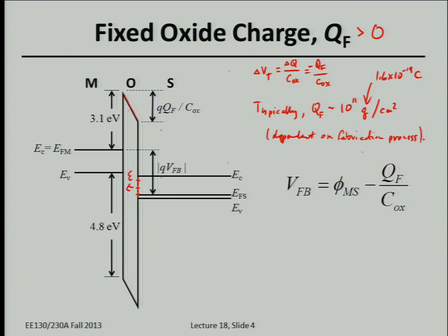So this energy band diagram shows you the flat band. If I give you this energy band diagram, you should be able to tell me it's a flat band MOS band diagram. That's because the definition of flat band is that the energy band diagram is flat in the silicon. Now, the reason why it's not also flat in the oxide is because of fixed charge or some charge at the interface. So qualitatively, if somebody were to show you this band diagram, you should be able to tell me there's charge at the interface between the silicon and silicon dioxide, because there's an electric field existing when there's a flat band condition in the silicon.